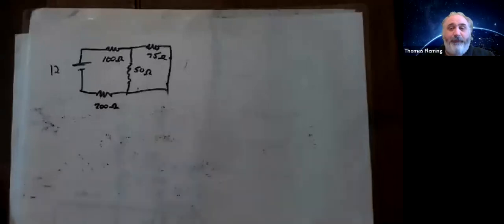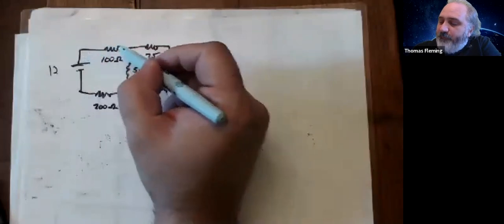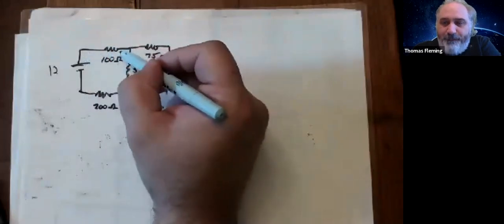Yeah. There's a reason I'm drawing the circuit like this, is because I'm trying to trap you. Right? I'm trying to show you that sometimes if you think, oh, they're across from each other, that means parallel, it'll mess you up. And this is one of those times. Because to be in parallel, if I go through one, I can't go through the other. But look, if I come out of this circuit, I'm going to go through that 100 no matter what, right?